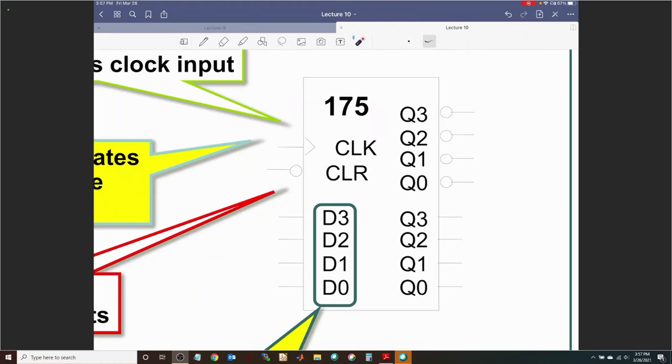If you want to cascade decoders, then you want these signals to be active low versus active high so that you can use them in interesting ways. One responds when it is active low, the other responds when it is high. So it's useful to have a combination of active low and active high control signals.